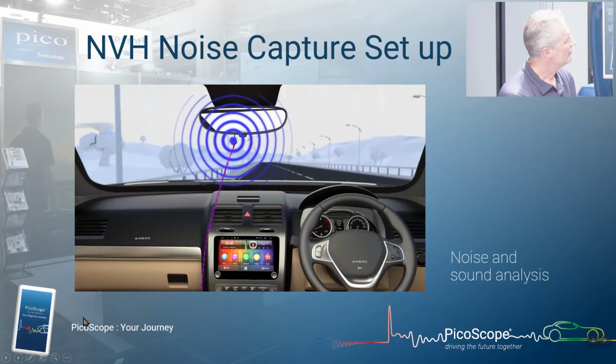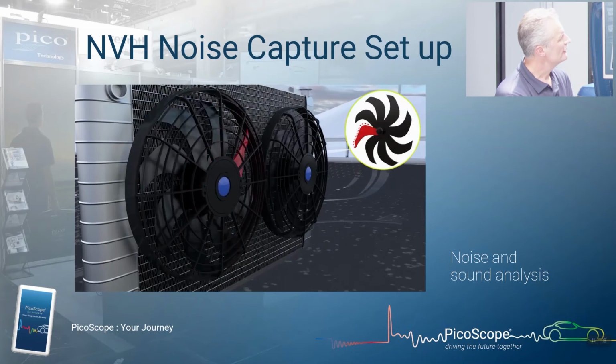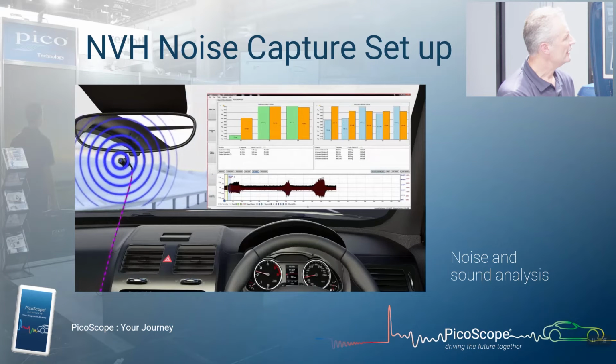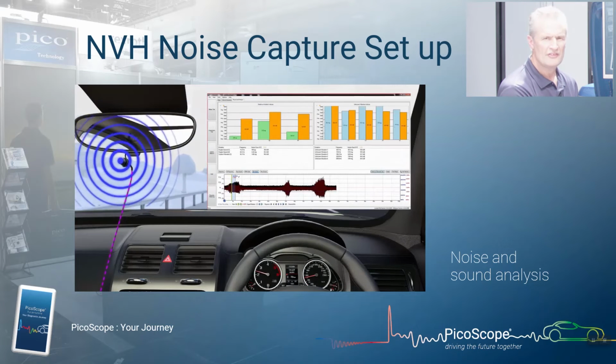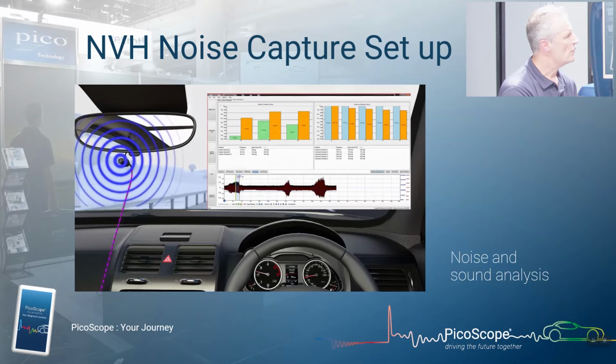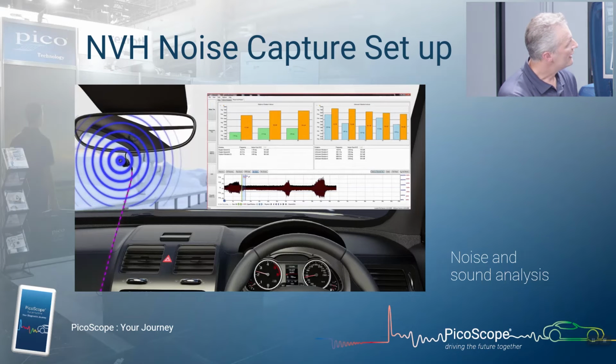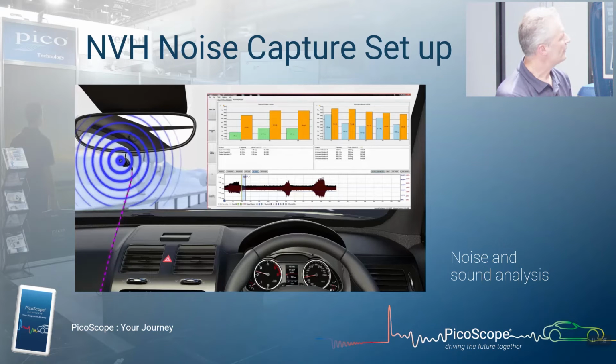So there is our connection. Here is our microphone. Remember, it is a microphone, it captures all noises. And here is one of those frequencies that is not linked to engine speed in any way. It's an electric fan. So it's going to be an unknown vibration because we won't have any link to the frequency of that component. So notice there we've got periods of high acceleration, high vibration and high noise level, which is captured by the microphone. Periodically, because remember the cooling fan cuts in intermittently, it's not in all the time. And again, we'll see that as an unknown vibration.